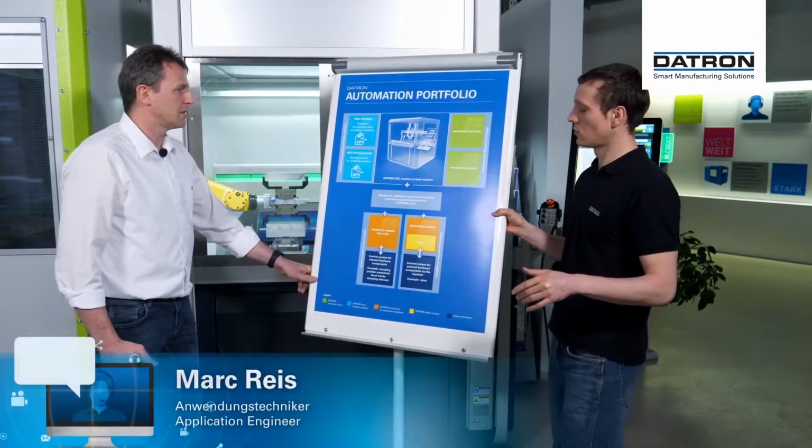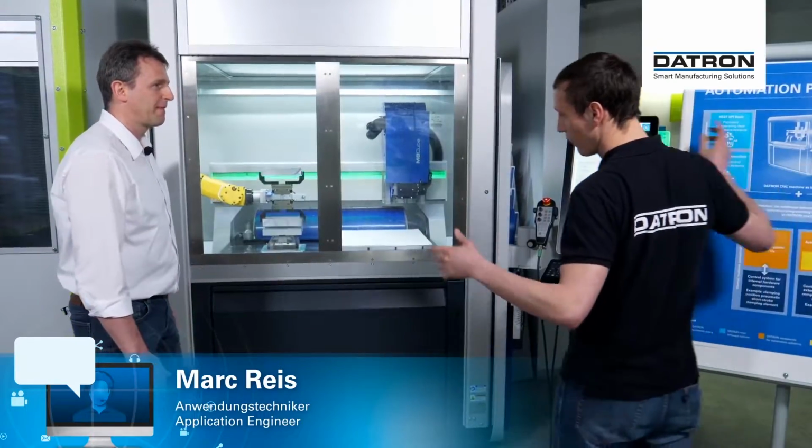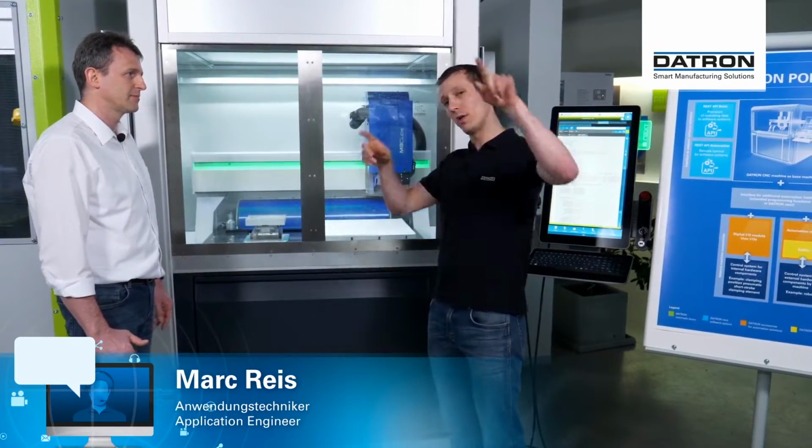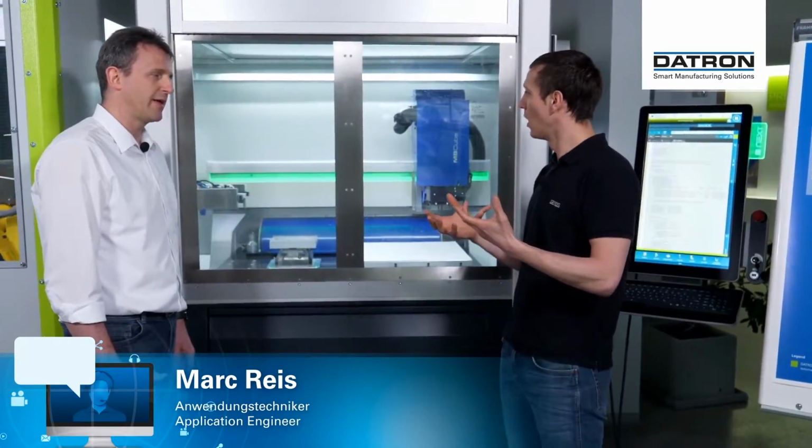To summarize, we have a parallel loop that controls all the safety signals, like the door, whether the chuck is closed, whether the robot is in its correct position, whether the spindle is on, so everything that is important for our entire milling, loading and unloading process. It's checking this permanently and externally of the NC code.